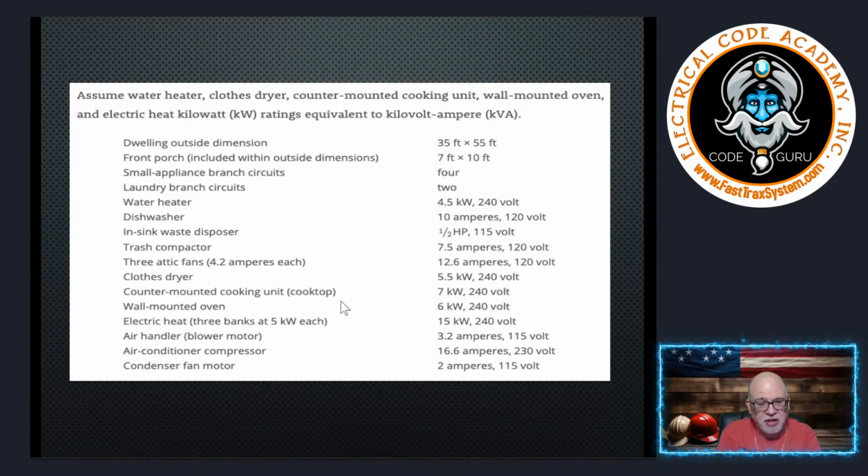It was a garage, but they changed the garage door and put a wall across it. They framed it in and created a separate entry into it. Quite interesting, but it was most certainly an ability to expand it to a habitable use, and it was expandable as future use. So that's why we take it into consideration, and that's why the garage was taken out. Whereas now it just talks about the application of spaces that are not adaptable for future use and open porches. Okay, so yep, absolutely, it's included now in the 2023 edition.